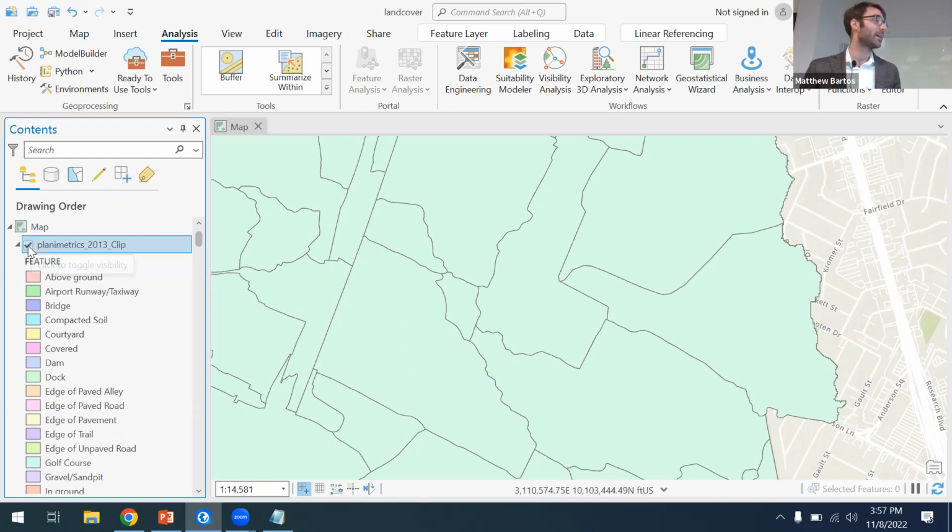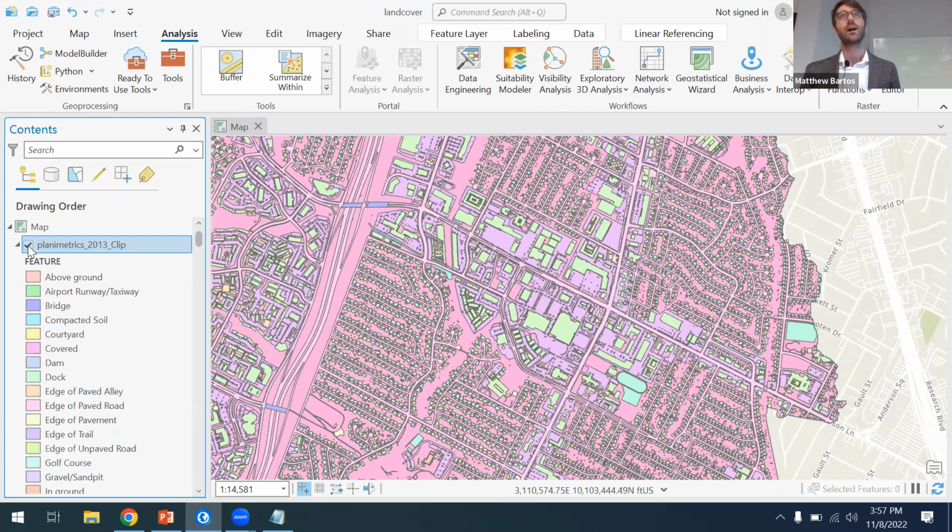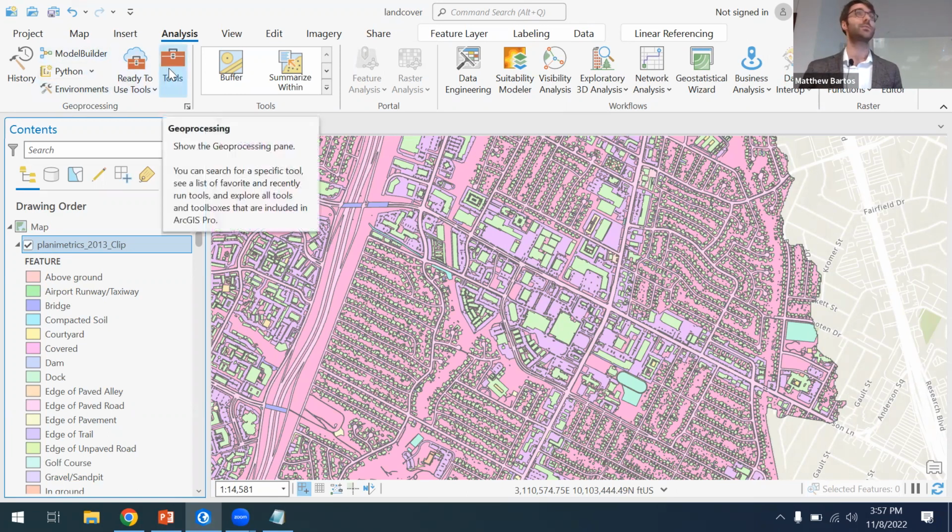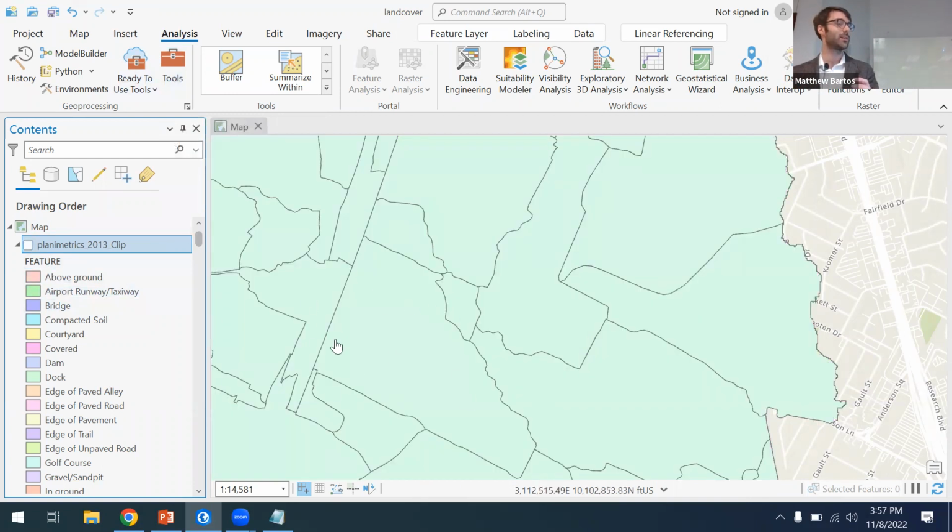And to do that, I can teach you a cool trick. Within ArcGIS, there's a function to basically do exactly that, and that's called the spatial join. Has anyone heard of spatial joins? Okay. So what it's going to do is find, for each of those subbasins, which polygons from the planimetrics intersect with that subbasin, and it's going to give us an output file with the breakdown. Basically, it'll give us the name of the subbasin that each land cover polygon in the planimetrics file is inside of.